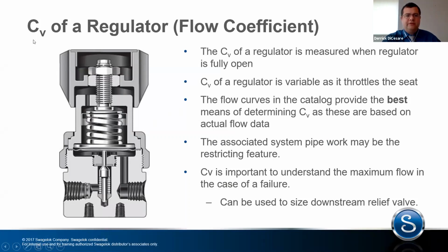Like we talked about, the flow coefficient of a regulator is measured when the regulator is wide open. So it's good to know, but we don't want to size based on that, because if you are, then you're not using it as a regulator. We're using it as a flow control orifice. So it's good for just a quick look. If you're using the calculator and you say, hey, I need a flow coefficient of 0.2, you know that your regulator should be at least 0.2 in most cases.